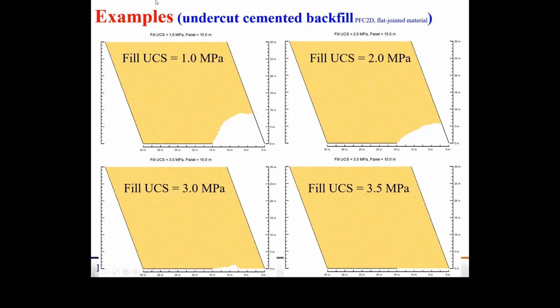This would all be removed, this material up above. You don't want to leave those openings in the mine, so what you do is you put in cemented backfill. After it's cemented, you come a little bit lower and you excavate more.